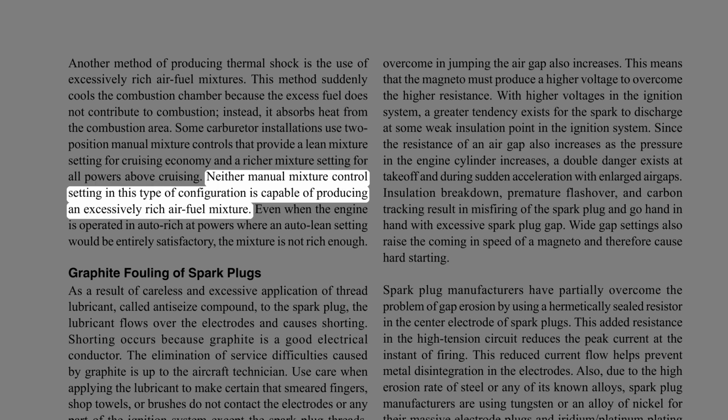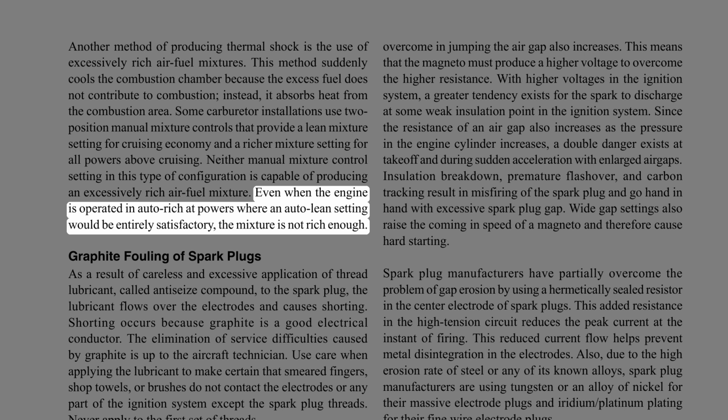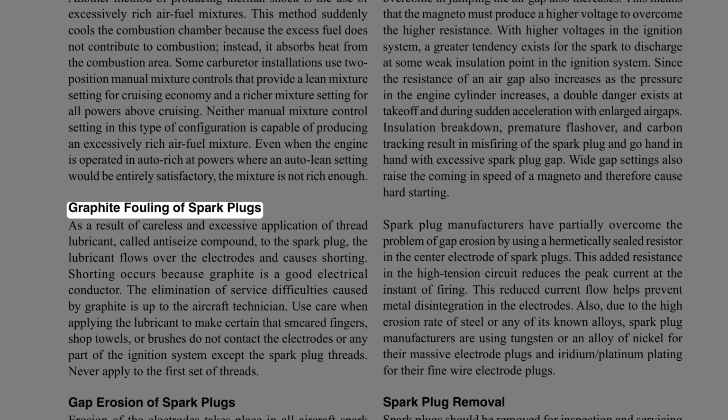Neither manual mixture control setting in this type of configuration is capable of producing an excessively rich air-fuel mixture. Even when the engine is operated in auto-rich at powers where an auto-lean setting would be entirely satisfactory, the mixture is not rich enough.